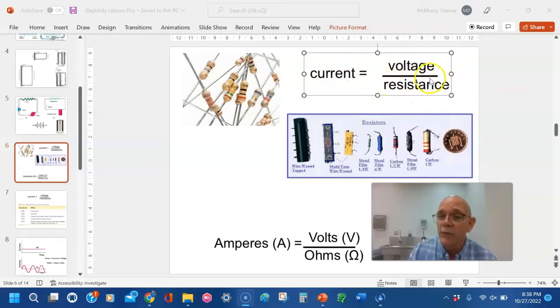You can have a fairly high voltage, but for example, if your skin is dry, you have like 5,000 ohms of resistance. On the other hand, if your skin is wet and salty, you may only have 100 ohms. That's a 50 times difference in how much resistance your body has, okay? So it is technically the amount of current that goes through your body that's dangerous or not. But obviously voltage is going to affect that, but so is the resistance. So it just depends. If you have a high voltage, but you also have a high resistance, then it may not be harmful. It also depends what part of your body it goes through.